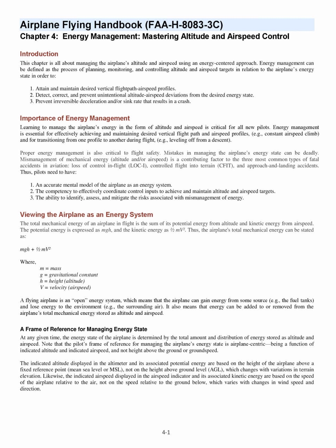Mismanagement of mechanical energy, altitude and/or airspeed, is a contributing factor to the three most common types of fatal accidents in aviation: loss of control in flight, LOC-I, controlled flight into terrain, CFIT, and approach and landing accidents. Thus, pilots need to have: 1. An accurate mental model of the airplane as an energy system. 2. The competency to effectively coordinate control inputs to achieve and maintain altitude and airspeed targets. 3. The ability to identify, assess, and mitigate the risks associated with mismanagement of energy.